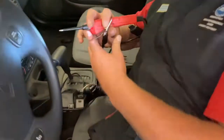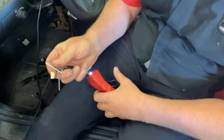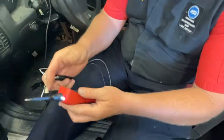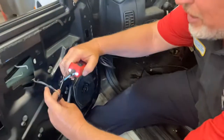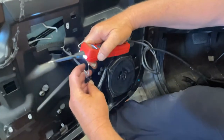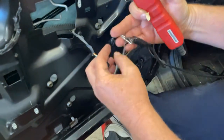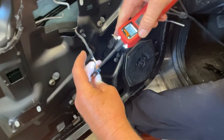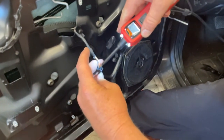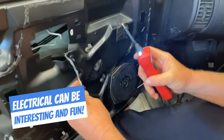So you're using a technique which we call back probing. Okay, so you could use this to turn things on and off. So your back probe, you'd put this into the back of a wire, and then you can make that be ground using the clip, and then you would apply power to another one. So this is actually for the door locks. So let's give that a try.